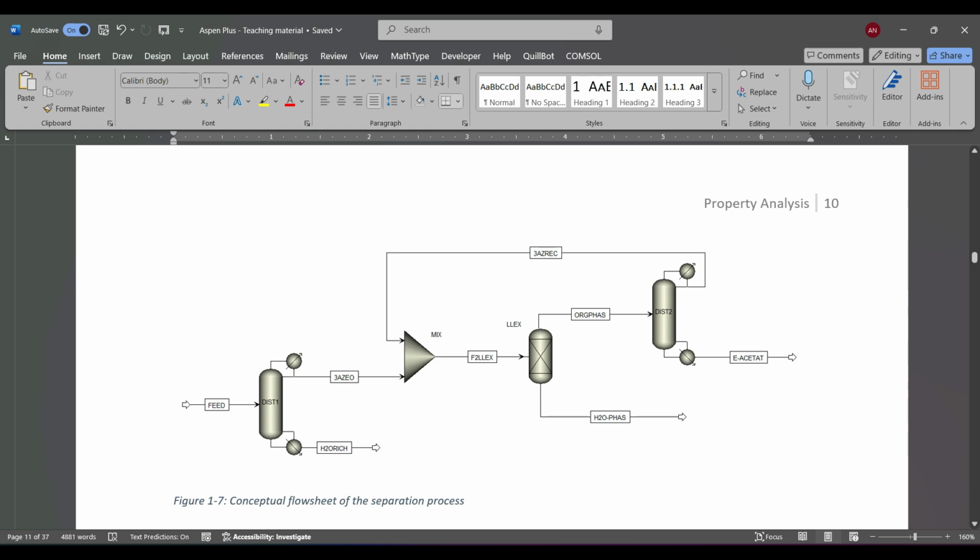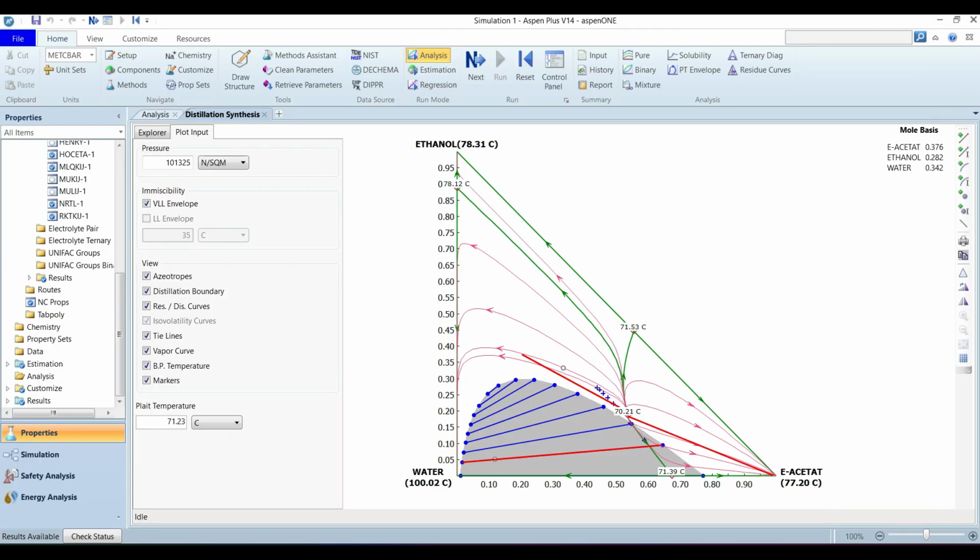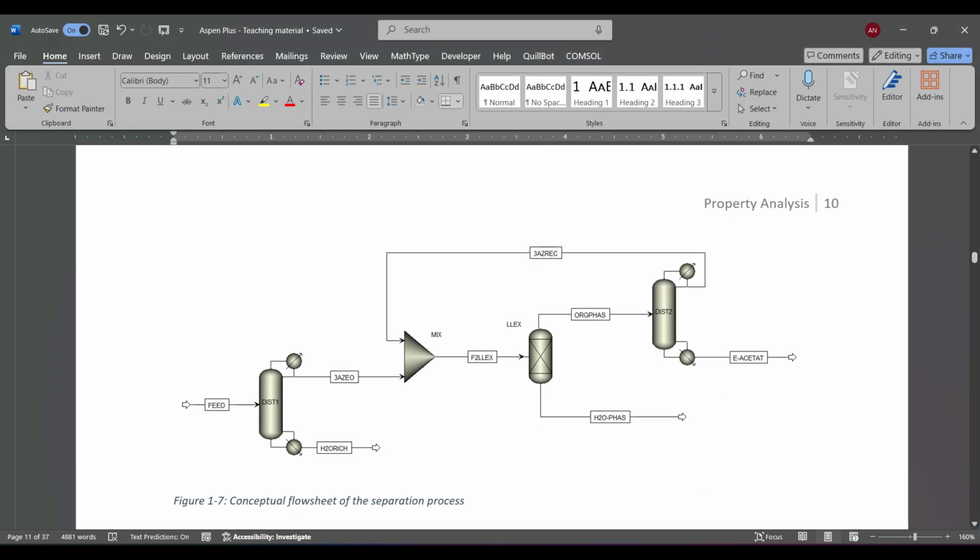So we have an equimolar feed of the three components, put it into the distillation column, and get a nearly water-rich product from the reboiler, and the ternary azeotrope from the condenser. There is a mistake over here, we were adding water over here. So in this mixer we have to add water. So put more water over here, just move from this 70.21 point to this inside the envelope. Just make this correction. There should be a water stream entering this mixer as well.